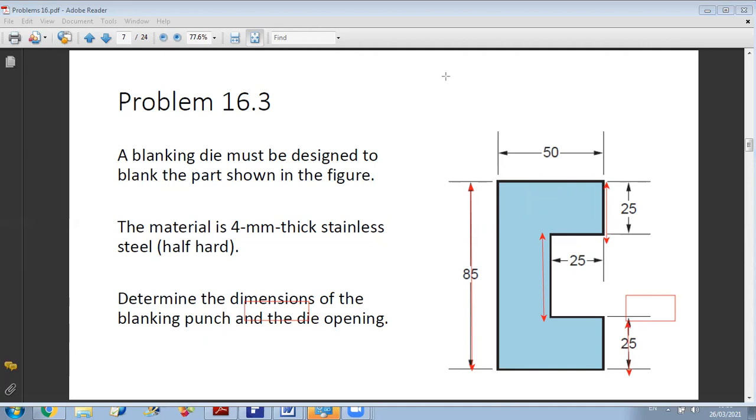because if you want to draw it, you should take a clearance from two sides. So you have here 2C, okay, and you have here 2C. So you will have C from this side and C from this side. So in total, it will be 35 plus 2C. Okay.